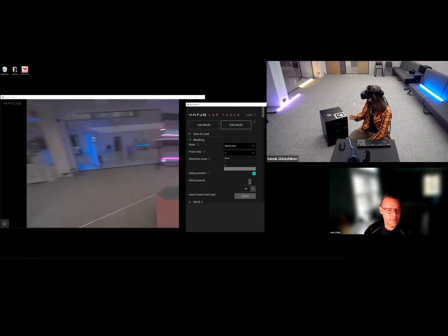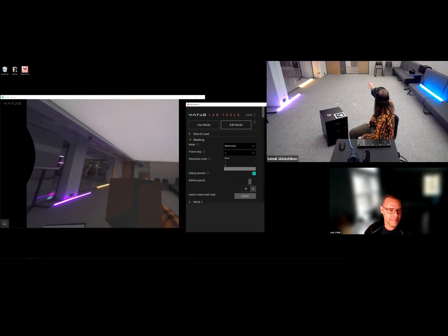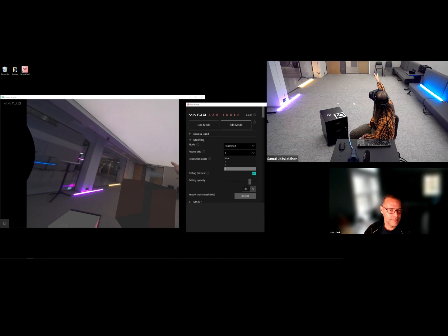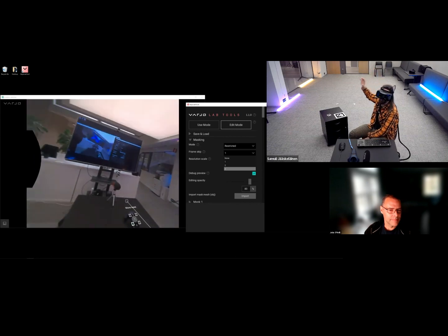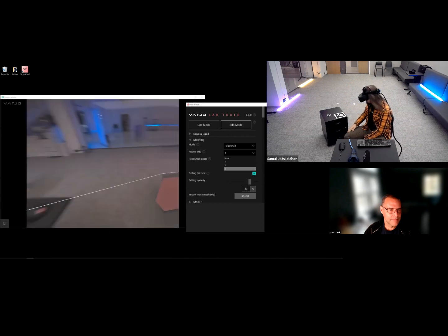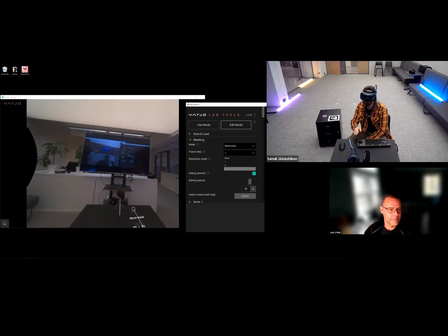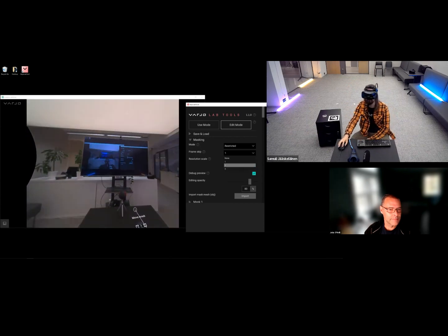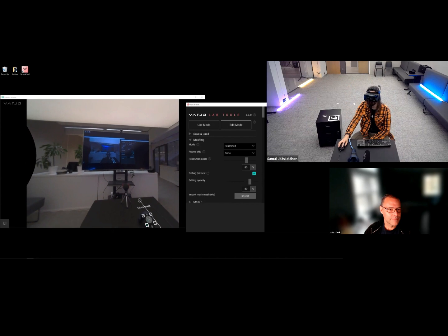For example, if I would mask off the ceiling here, and otherwise this would be a chroma room, that mask would never move. So then I could easily have a frame skip value that is quite high. But if I have moving objects like this cabinet, we want to keep this as low as possible, so they are more responsive when they are moved.